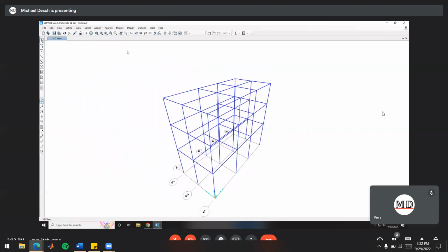If you need to zoom in and zoom out, these magnifying glasses here work as well. If you go and zoom yourself off into some remote corner of the environment and can't find where you placed your structure, there's this one right here called Restore Full View. It's got the solid circle inside the magnifying glass there. That's really useful. That brings you back and it centers your view on the structure. So just in case you accidentally manage to zoom way in and get lost or something like that.